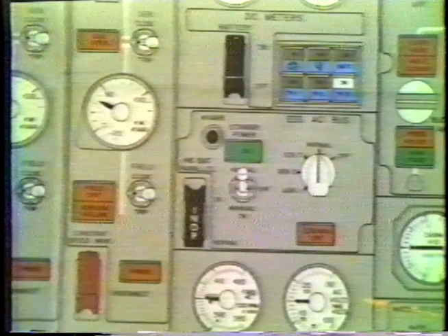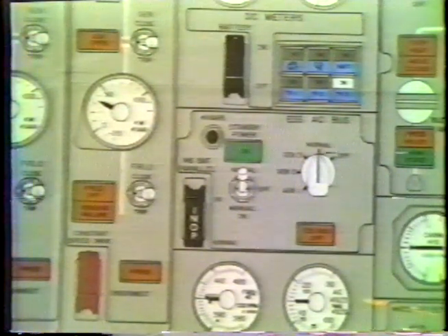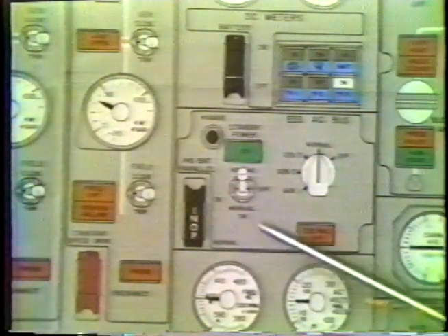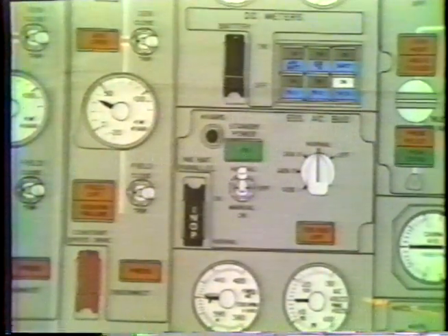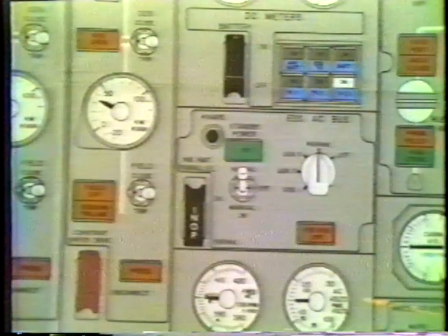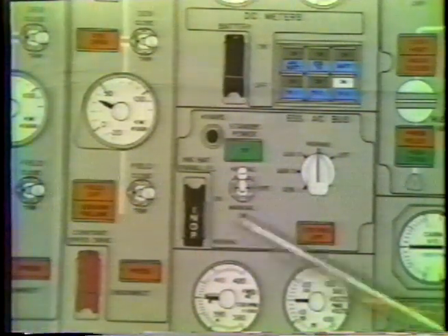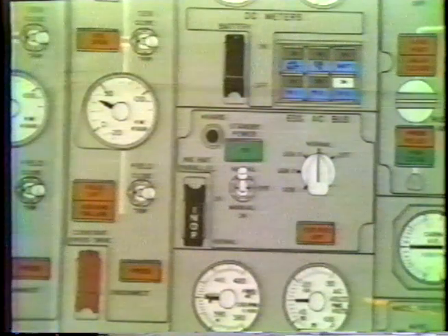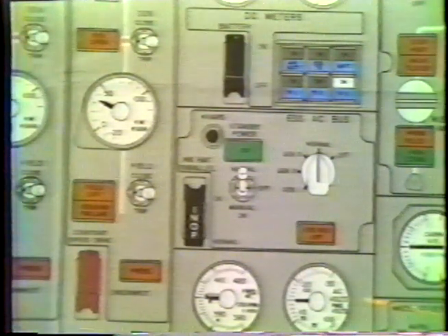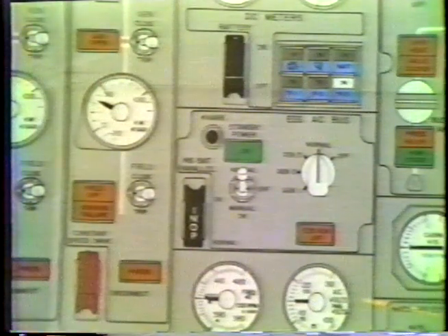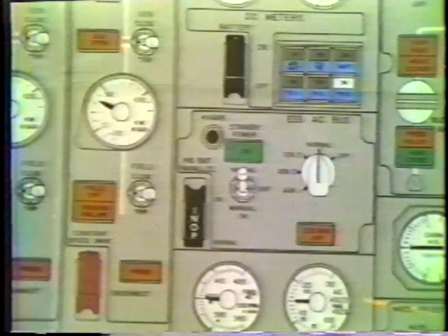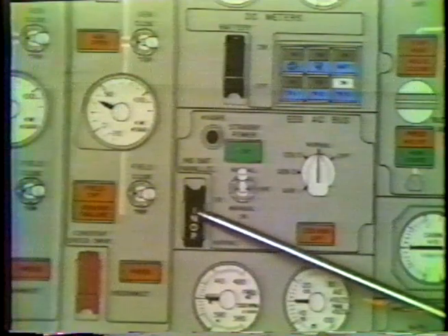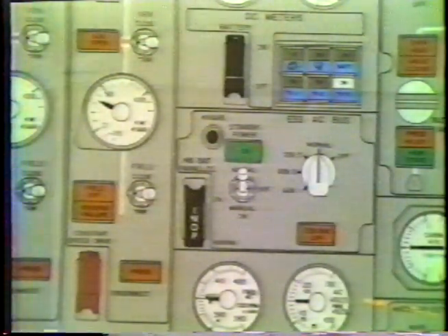The INS battery normally should be able to keep the INS running for approximately 15 minutes. However, when you parallel it, you can keep the number 1 running for approximately 30 minutes. However, once you operate this switch and move the battery off INS number 3 onto INS number 1, the INS number 3 is inoperative and can't be used anymore, even after power is restored. Another thing this switch requires to operate is the standby power green light to be on.